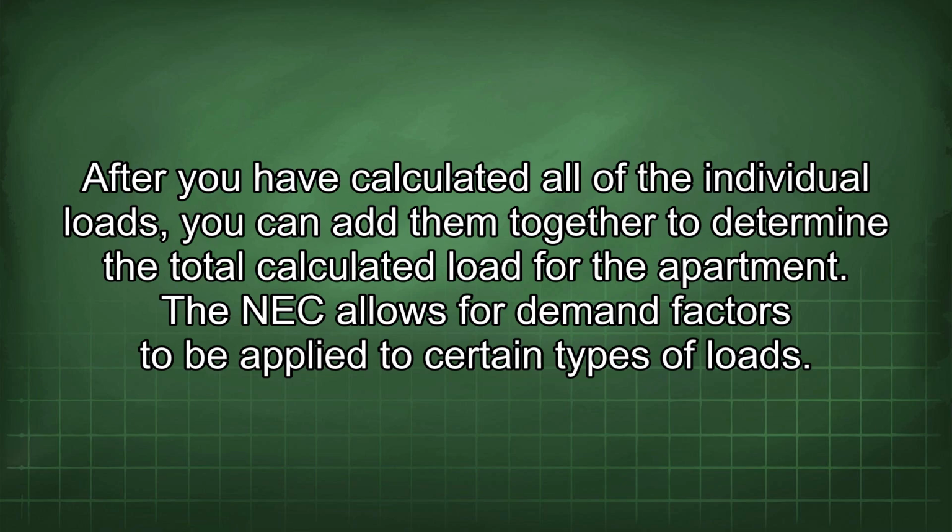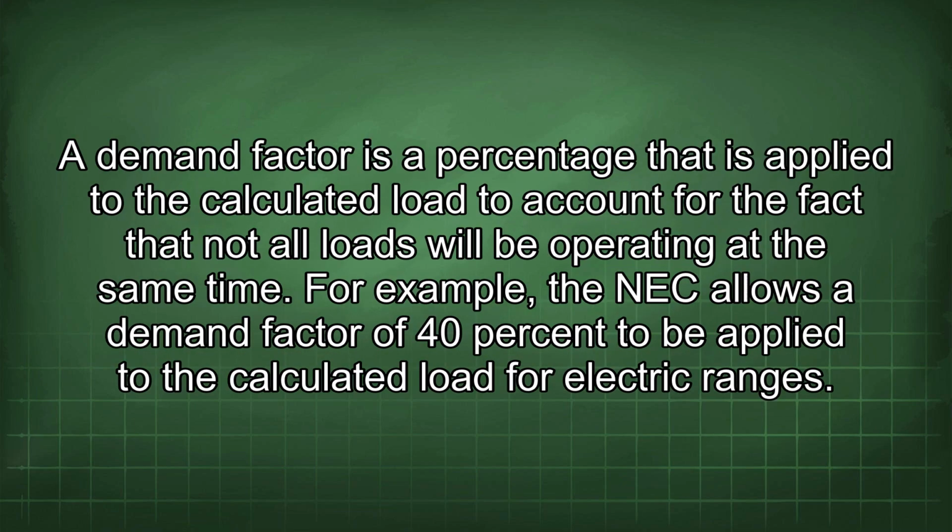The NEC allows for demand factors to be applied to certain types of loads. A demand factor is a percentage that is applied to the calculated load to account for the fact that not all loads will be operating at the same time.